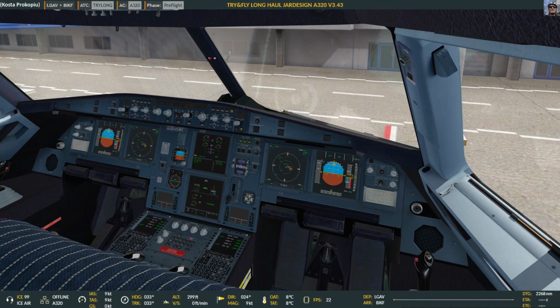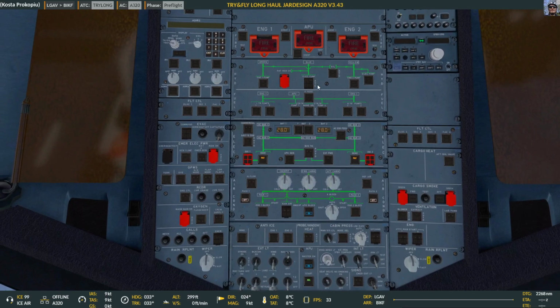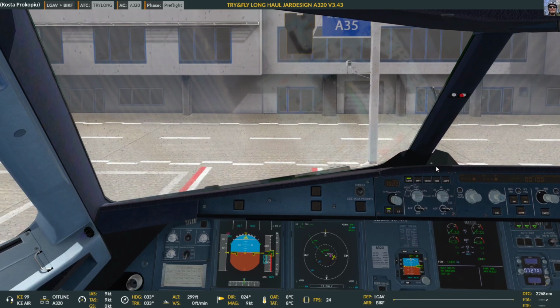Tow connected and bypass in and serving. Release parking brake. Right. So what do we look like here? I think we're fine. So let's make sure that we have the beacon on. We have the strobes on now. With the beacon on, Sam will remove the gate, and I think we are fine up here. I hope I haven't overlooked something. And parking brake off.